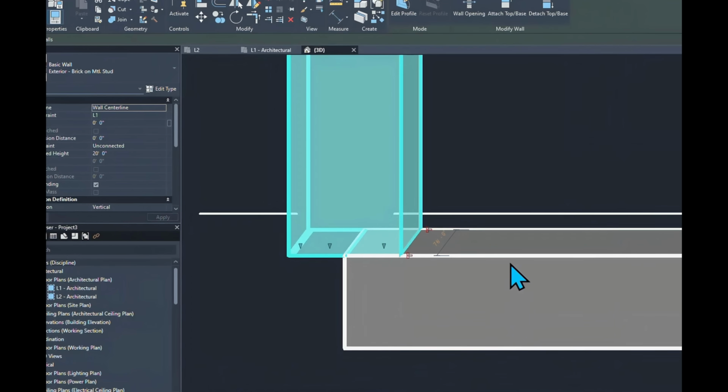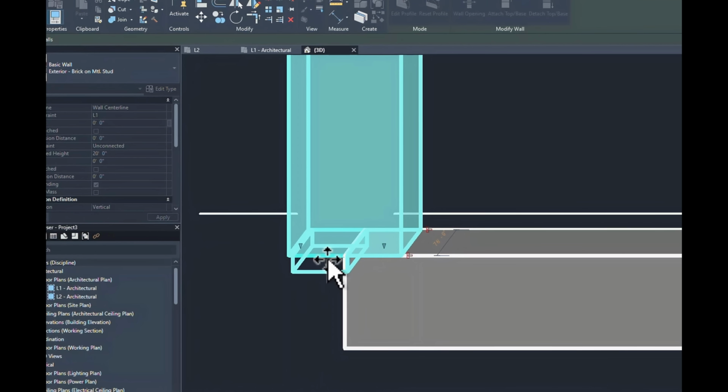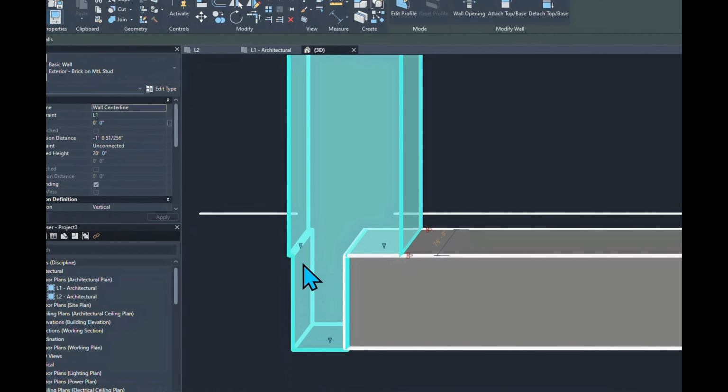And if you notice right now I have three types of arrows, right? One arrow is for the area that is all locked, and the two other types of arrows are for the layers or the areas that I unlocked, because I unlocked two locks. So right now, if I grab this and bring it down, you can see that portion stays, but only this portion of the wall is going to come down. So I can basically adjust it. Each time that you unlock a lock on the layer, one arrow is going to show up over here for you so you can grab in and adjust, right?